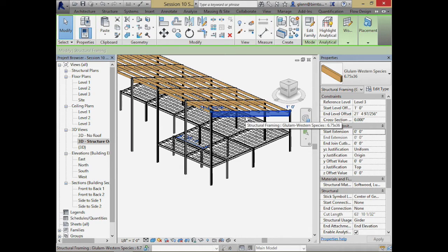So if you haven't seen glulam beams, they're actually really cool. What they do is take layers of 2x lumber and glue them all together to make an incredibly tall stack. And glulam beams are very nice. They can span very long spans. You'll often see them used when you have a curving span, because they can form them with all the different layers to taper and follow any curve that you want. So glulam beams are really, really nice.